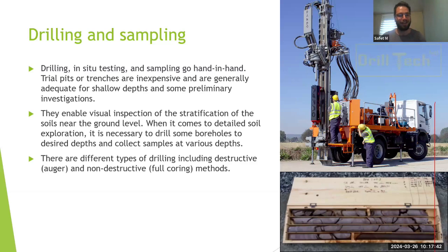They enable visual inspection of the stratification of the soil near ground level. When it comes to detailed soil exploration, it's necessary to drill boreholes to the desired depths and collect samples at various depths. Of course, there are different kinds of drilling that will depend mostly on your budget. We usually have two methods: destructive and non-destructive.